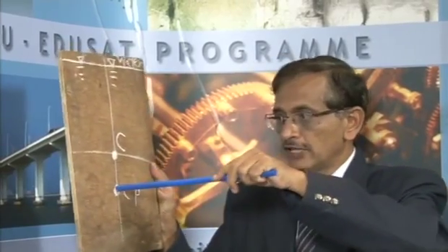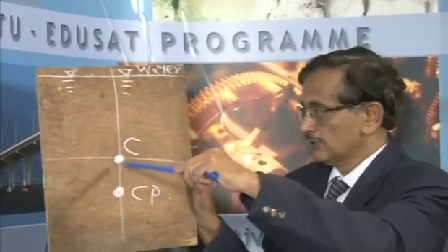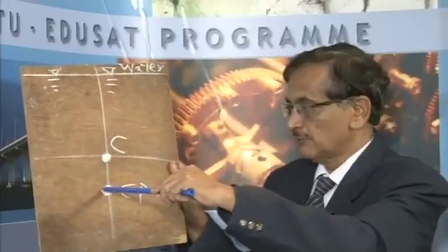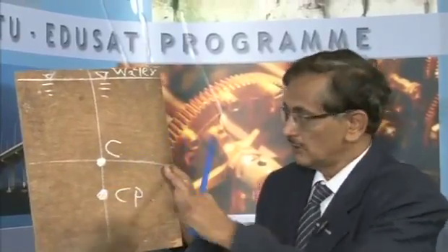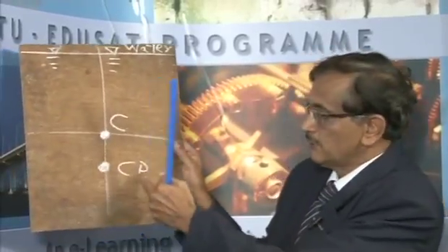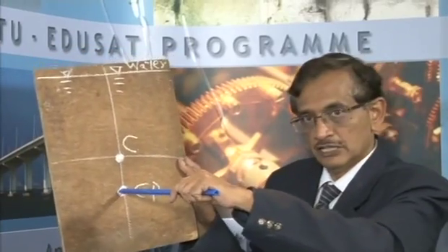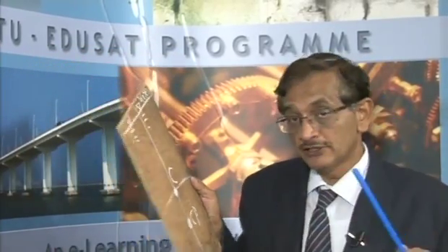In a vertical system, it is going to be like this. You can see here exactly. Centroid is here, center of pressure will be slightly below. The name is C for centroid and Cp for center of pressure, exactly like this. But one question arises: suppose instead of horizontal or vertical, it is inclined at some angle,